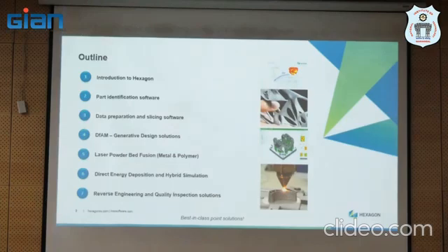So when I say optimization, it cannot be only stress-based optimization using any of the tools, even if we have Apex Generative Designer, Nastran or any other solution. Optimization cannot be only stress-based. It has to be from the thermal point of view, frequency and other aspects as well. But we can do that as well.